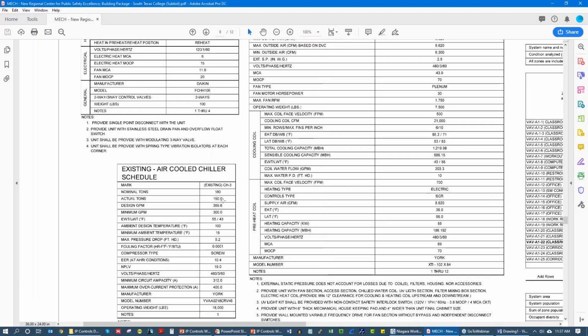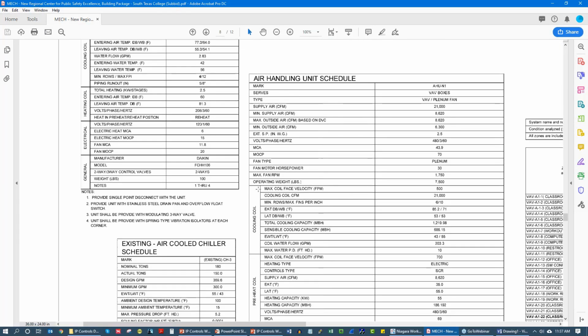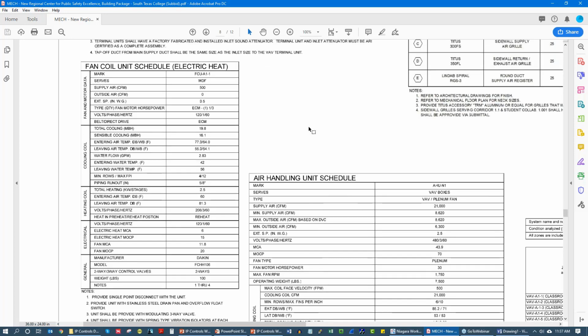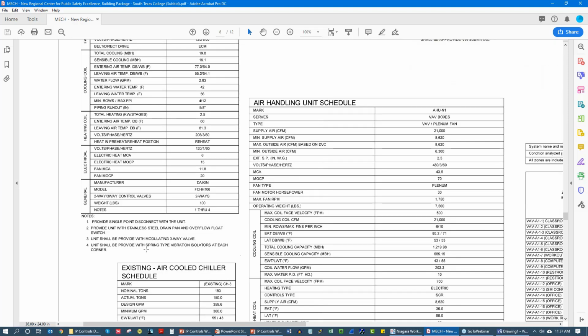We're running an air-cooled chiller, an air handler, and a fan coil unit. Now, if we're using that Honeywell controller with its 4-port switch, I technically have 2 ports left, right? Because we're using a bus or a ring, and I need 2 ports for each controller. So off of one controller I could do the fan coil, off another I could do the air handler, and off another I could do the existing air-cooled chiller. I could pull those in.